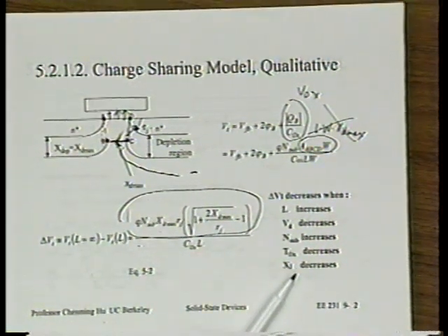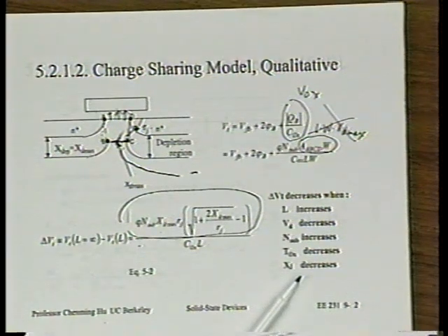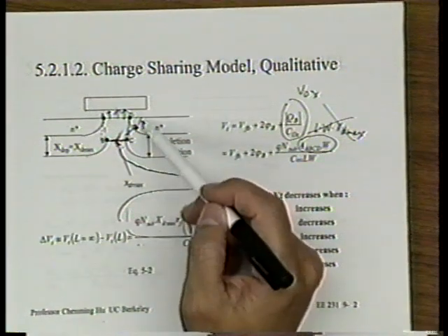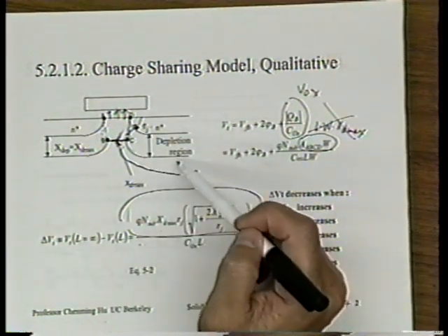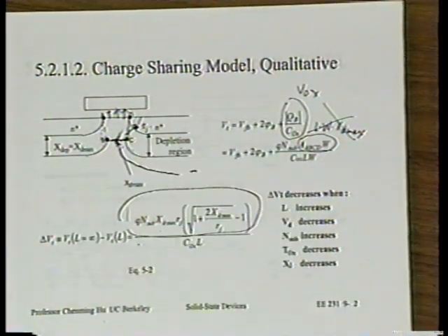Junction depth, thinner is better. Can you see that? If the junction depth xj is smaller, then the whole radius of this curve is better, then the trapezoid difference and rectangle difference is a little better. Is that right? Okay. So qualitatively, this gives us the correct effect.